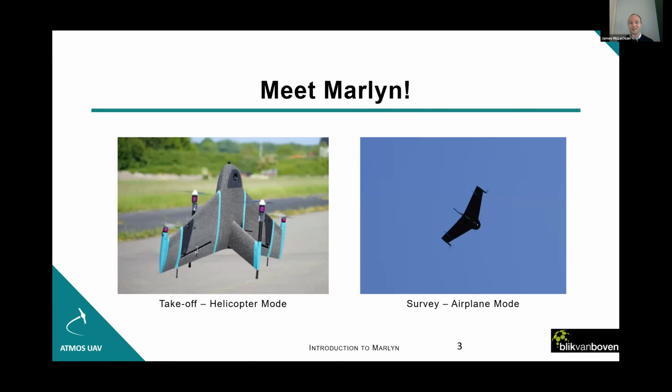And what it also does is it removes the disadvantages of a multi-rotor and the disadvantages of a traditional fixed wing drone. What are those? Well, typically with a multi-rotor, you're able to take off and land everywhere, but you can't really cover big areas. That's the result of the propellers being used to keep the whole weight of the drone in the air, so it's not that efficient.